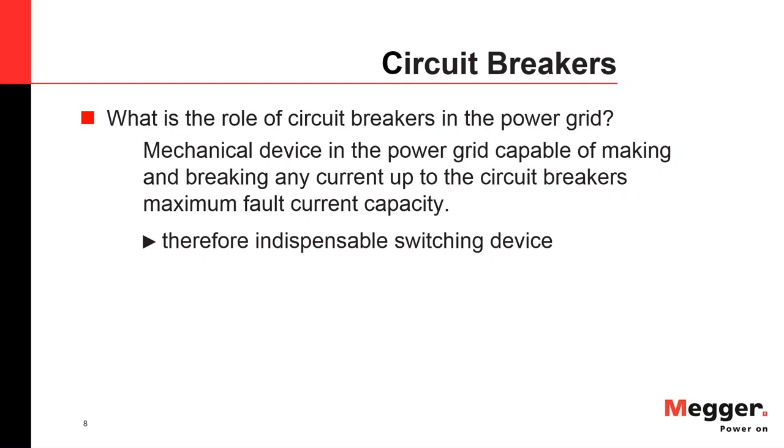That's not cost effective, but the circuit breaker can take care of all of these roles, while the other devices can only take on one of the duties, and they would fail, for instance, if you exceed their interrupting rating, or if you open a dead break switch under load. So the circuit breaker is really the universal apparatus to make and break.